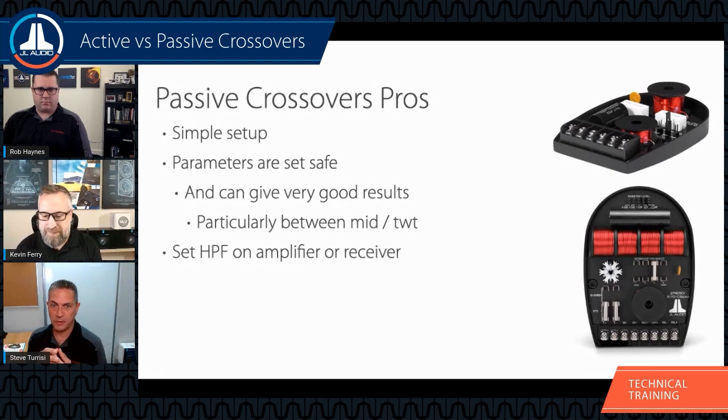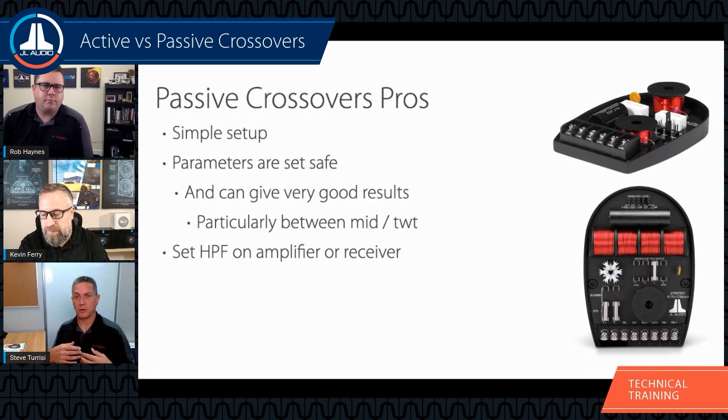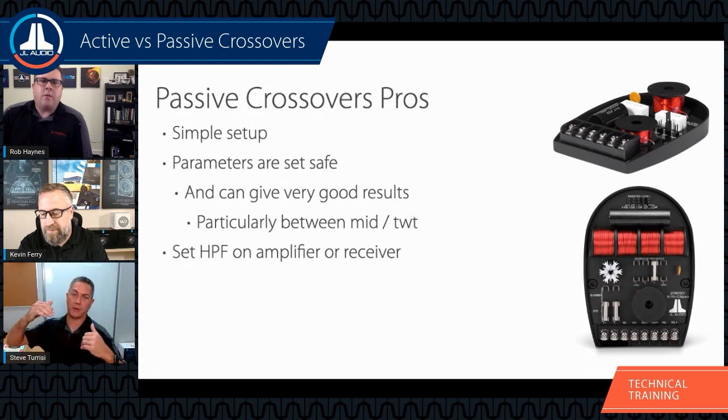But when it comes to these products here, there's an assumption that has to be made during the development of these crossovers. We have to assume where each driver is relative to each other. So as an engineering company, we do our best to approximate how far away a tweeter might be so that when the crossover works together, and again, Kevin mentioned earlier, one of the criteria is that you don't hear the crossover, you hear the result of the crossover. And because the drivers are not in one point in space, we have to anticipate how far apart they may be. And one question that often comes up is how far apart should the tweeter be from the mid-range?